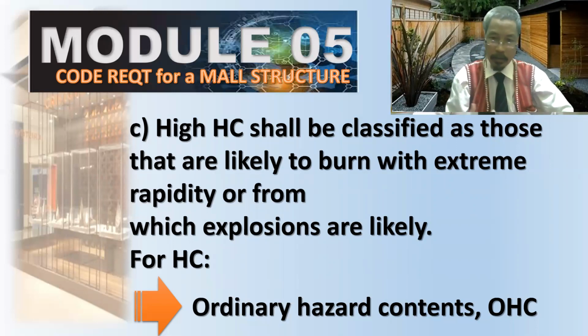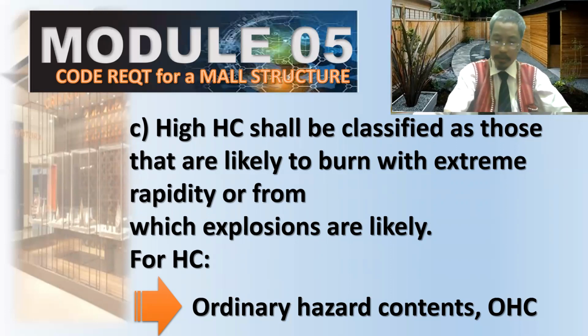And then talk with the owner, you have to, but most importantly, the AHJ should be able to approve our assertion that it is an ordinary hazard contents or OHC. Low hazard contents is LHC, and high hazard contents is HHC. We have OHC.